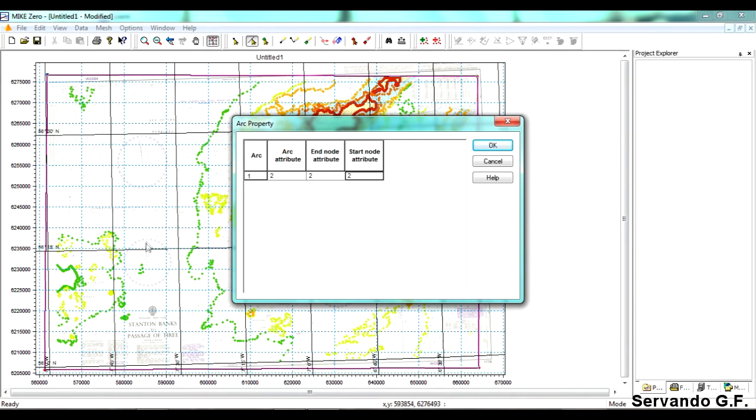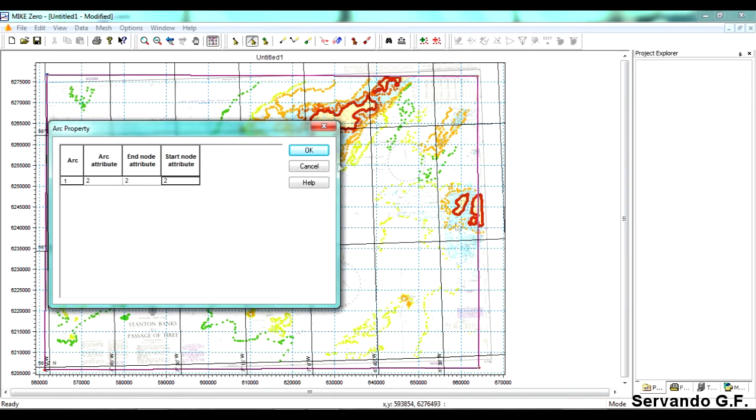Because if I generate waves coming from the south, I won't be able to control from where those waves are generated. Because the boundary is only one, the model will also generate waves from this boundary north and from this other boundary north. So I do not recommend building the boundaries this way, in a continuous way.